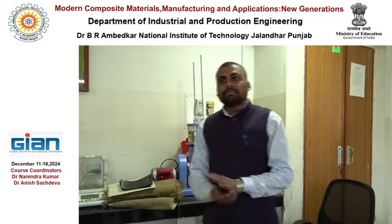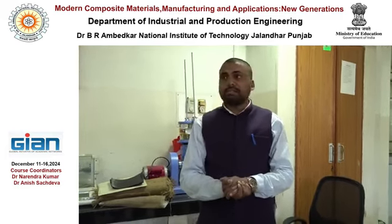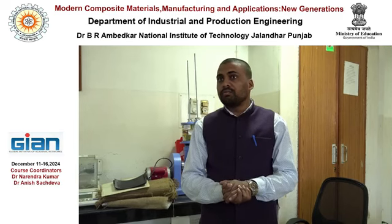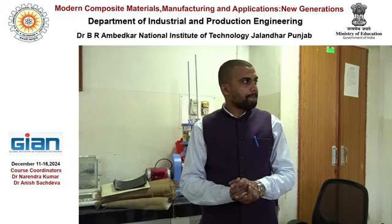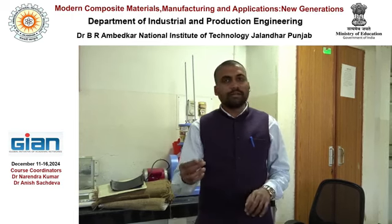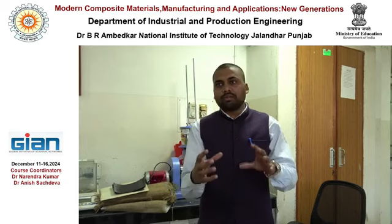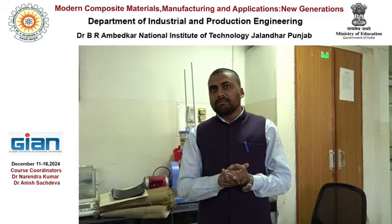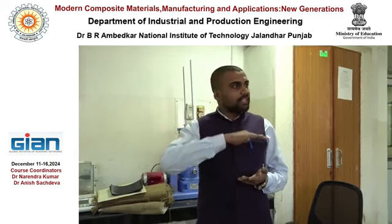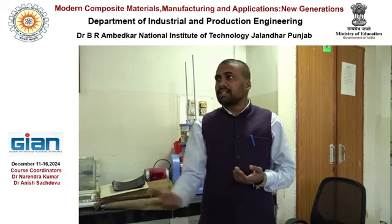So we will start with what the main problem is in composite materials. One of the major problems is voids. You may be aware of voids, porosity. Yes, void means air gap. Ideally, in the composite material we know that the matrix is the continuous phase, and reinforcement is the discontinuous phase.